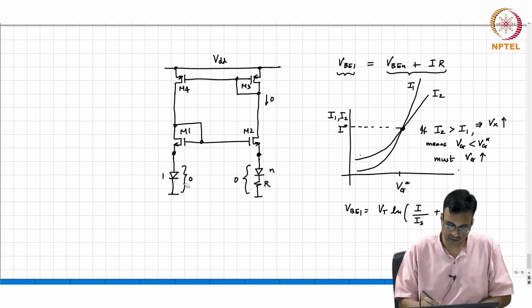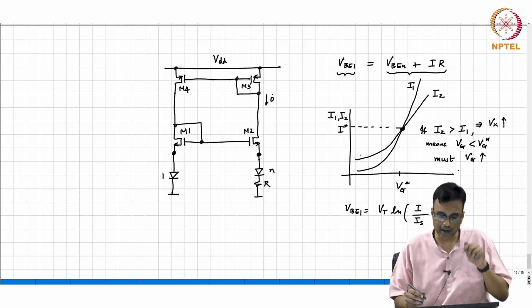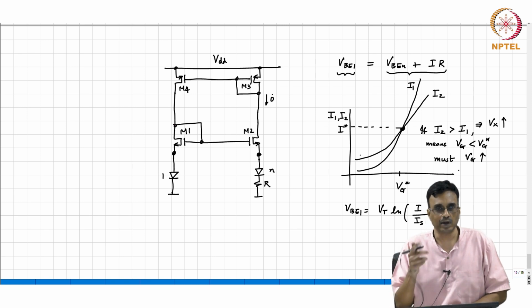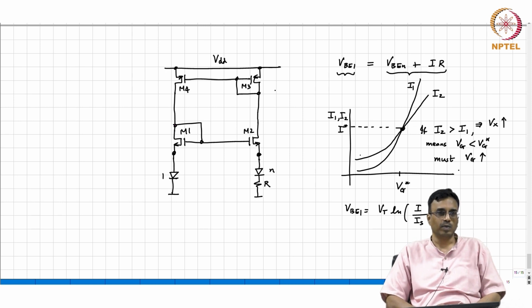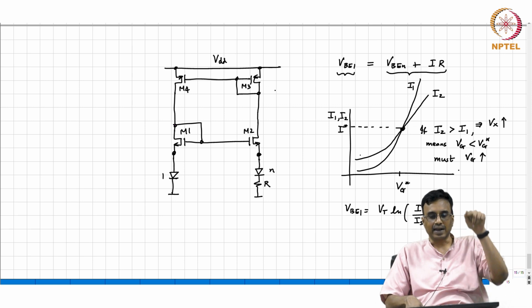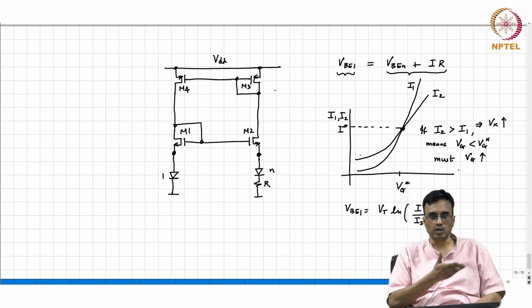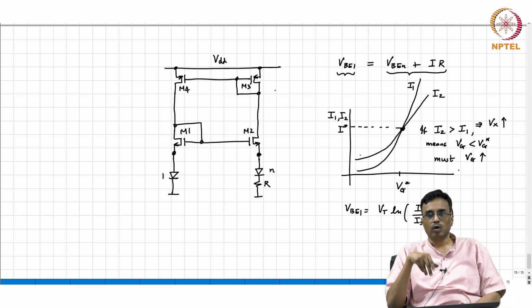Fortunately, it turns out that it is an unstable operating point, and if you slightly kick one side, it will come to the desired operating point. But when you are trying to make a product, you shouldn't be praying that something happens. Okay. So it's straightforward: if you know that the current flowing through any of these transistors is 0, the circuit is stuck at that all-0 state.